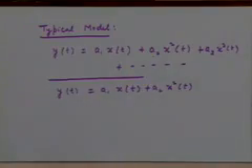Now how does this distortion differ from the linear distortion that we have discussed? In one very, very important and very significant way. If you remember, I had made a comment when we talked about linear distortion, that linear distortion which arises due to non-ideal characteristics of the channel in terms of its transfer function can only do something good or something bad relatively to different frequency components that exist in the message signal. But it cannot create additional frequency components, isn't it? A linear filter essentially affects whatever frequency components are present in the message signal.